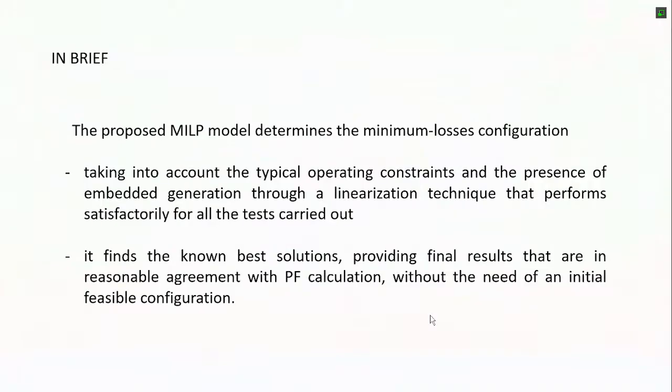This was in brief the proposed mixed integer linear model. It is one of the methods, but I have already explained why we have done these studies. It determines the minimum loss configuration, taking into account the typical operating constraints and the presence of embedded generation through a linearization technique that performs satisfactorily for all the tests carried out.